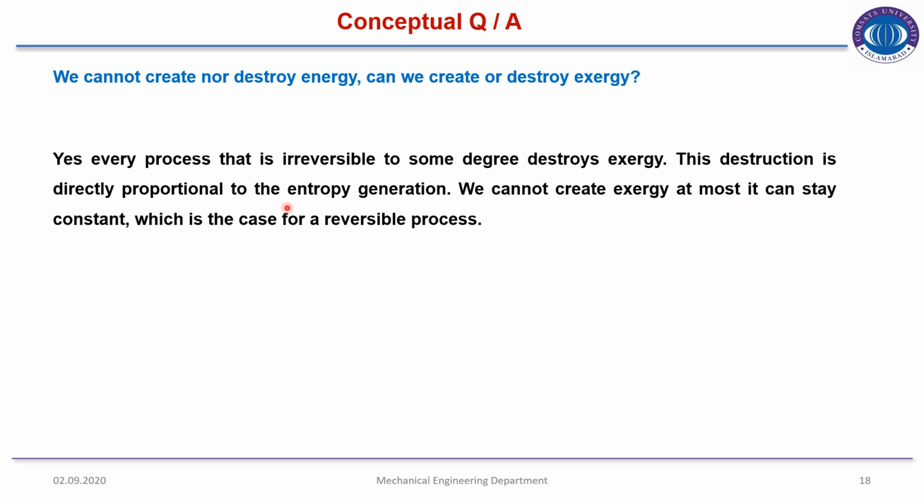This destruction is directly proportional to the entropy generation. We cannot create exergy. It remains constant in the case of a reversible process. So the question asked was, can exergy or available energy be destroyed?